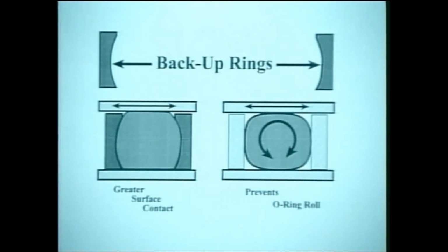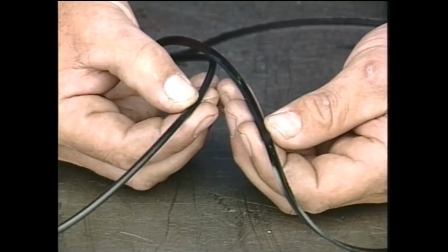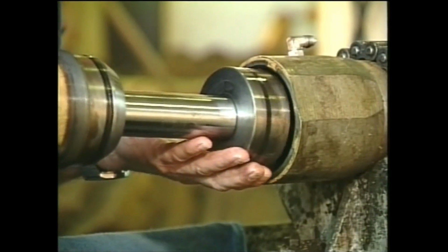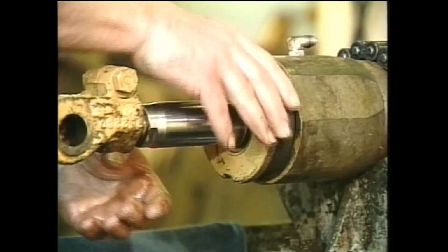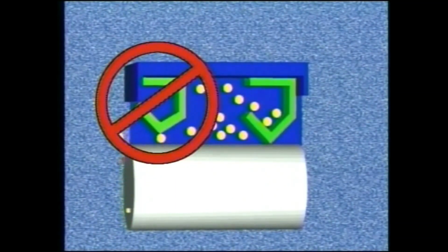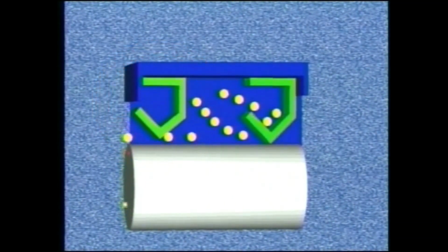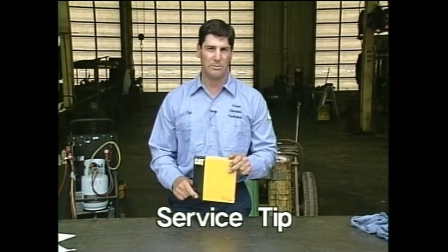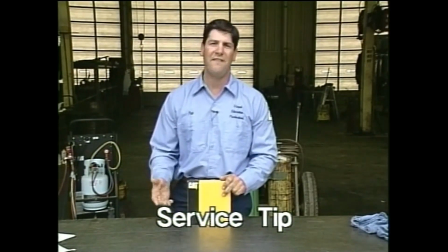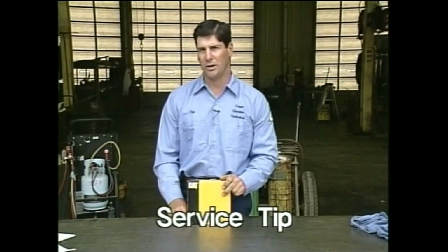Some manufacturers use O-ring seals and backup rings next to the O-ring to prevent the O-ring from rolling. Carefully examine the backup rings, as some have a concave surface to fit the O-ring. Be careful when installing the piston into the cylinder bore to prevent the new seals from rolling, folding, cutting, or tearing. When installing lip seals on pumps and motors, be sure the lip of the seal faces inward toward the pressure side. Otherwise, the pressurized oil will leak under the lip. Always contact the manufacturer for correct replacement parts. Will-fit seals and hoses may fit, but may not be compatible with hydraulic oil.